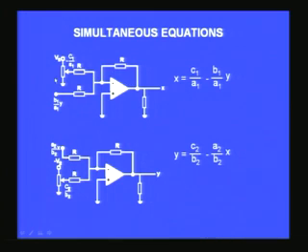What I have done is I have taken b1 times by a1 times y. I assume b1 by a1 times y is available at this input. At this input, from a voltage source I obtain minus c1 by a1 times this voltage Vs. This I apply. This feedback resistor is R, this also is R, therefore this summing amplifier has a coefficient of 1, R by R in both, but I am applying it to the inverting input, and therefore I am going to get all of them with a minus sign at the output.